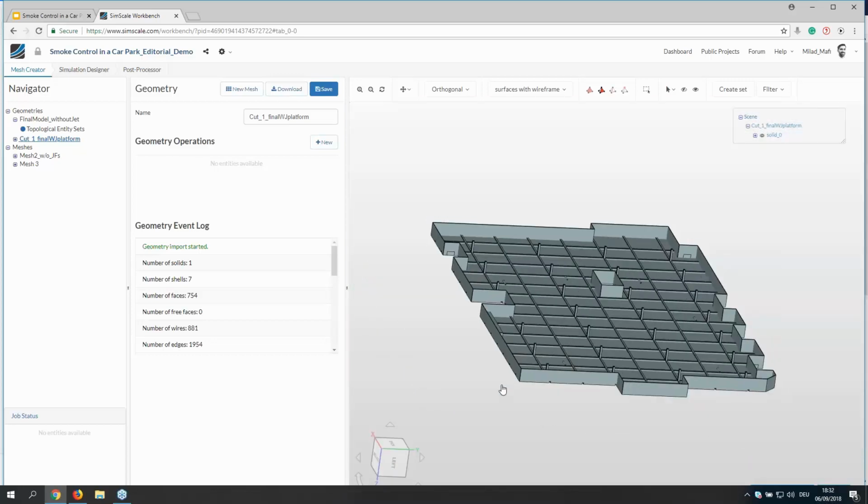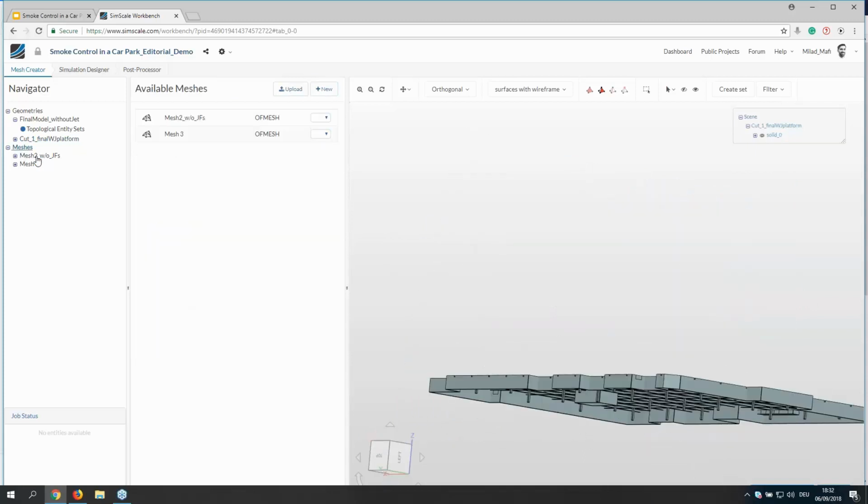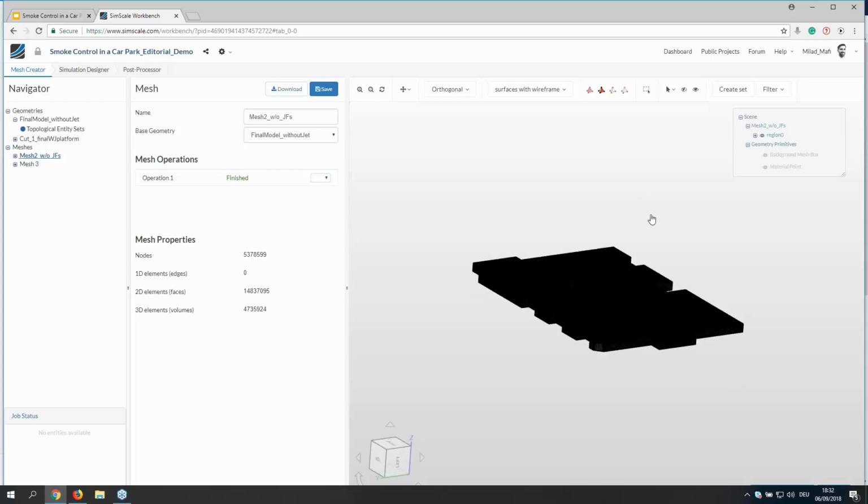And the first thing you need to do is a step we call meshing. Meshing is the process where your continuous CAD model, your continuous domain of your CAD model, is transformed into a discrete model, which means we are dividing our model into small sub-models of solid cells.